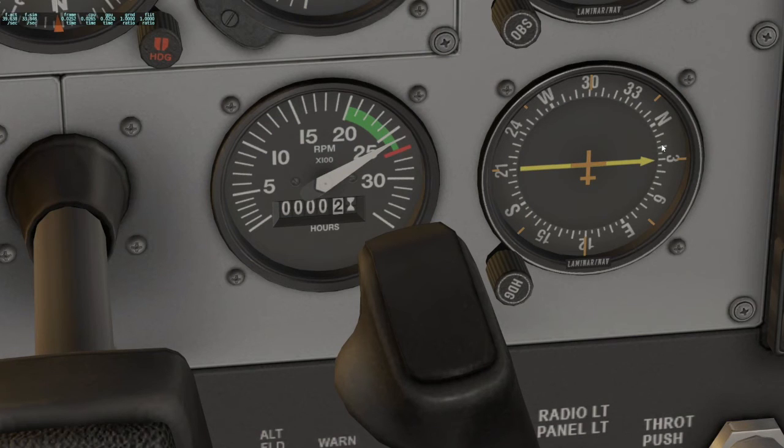We now follow the steps that we've learned about intercepting inbound radials, and we're going to measure. Here's 30 degrees, 300 to 330. There's another 30 degrees. The first thing we're going to do is fly opposite of the inbound radial, and parallel to it. That means we're going to have to fly the 300 direction. That's the first thing, 300. Then we're going to go abeam to it, and then we're going to intercept inbound.